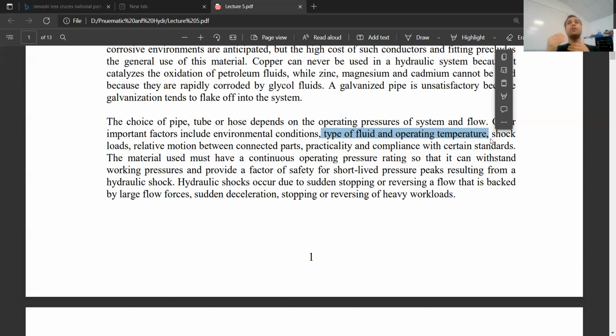If the temperature of the fluid is very high, there are two things. One is the melting point of the pipe. The other is the working temperature of the pipe through which we are transmitting the fluid. The working temperature of the pipe is very important. The working temperature is far lower than the melting point, usually about 0.4 times the melting point. So if we are passing hot and cold fluid, hot and cold, we are actually making the material creep.